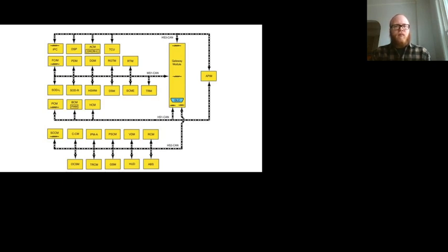This is our most modern of the diagrams. I've got 1, 2, 3 CAN networks, high speed, and 1 medium speed network. And now that we're into the realm of having 4 different networks, we've overfilled our data link connector to the point at which we need to have this gateway module. So this is a good time to take a little walk down memory lane and talk about the history of the data link connector.